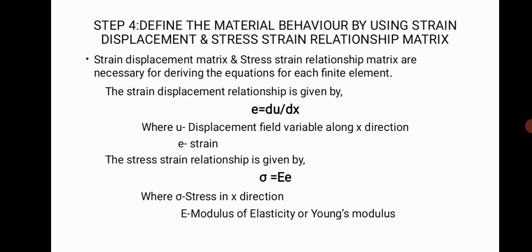The stress strain relationship is given by sigma is equal to capital E into small e, where sigma is the stress in x direction, small e is strain, and capital E is Young's modulus or modulus of elasticity.